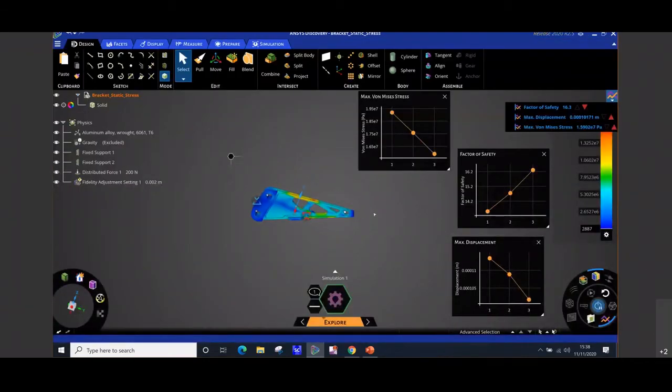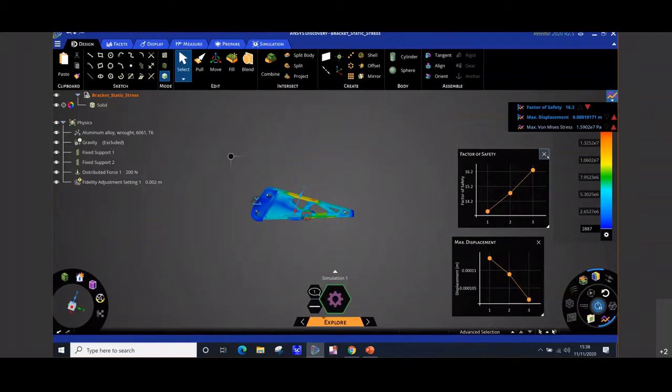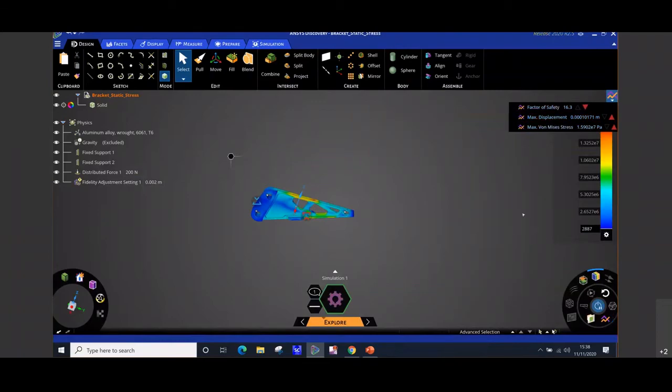You basically, again, those of you familiar with SpaceClaim, you can set a dimension as a group entity, and that parameter basically can be looped between a minimum and a maximum with 5 steps or 10 steps or whatever. You can do multiple variables, so you might do 3 variables with 5 steps each, and then run that parameter study. What it does, it runs each simulation result.